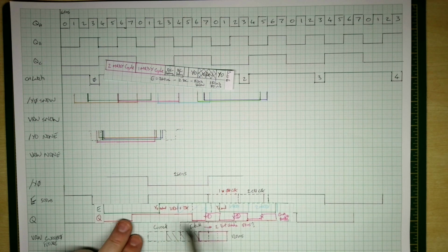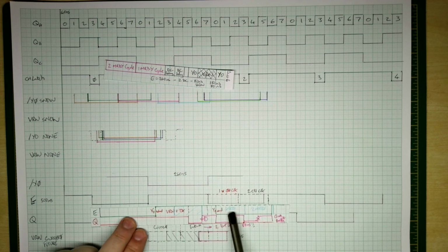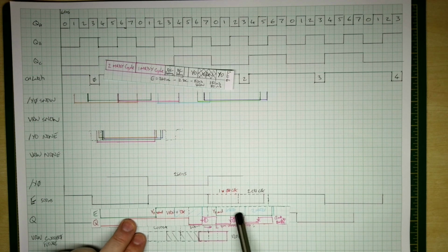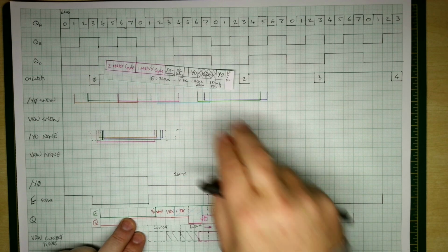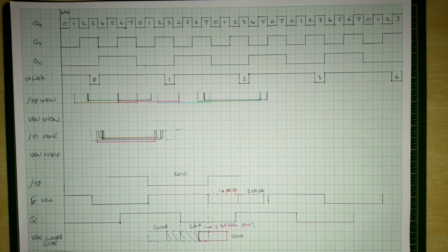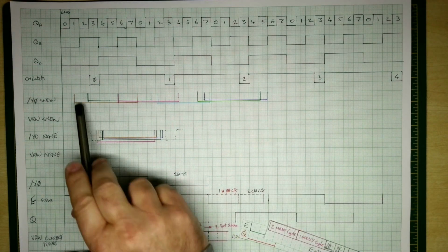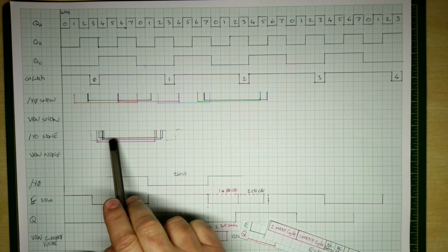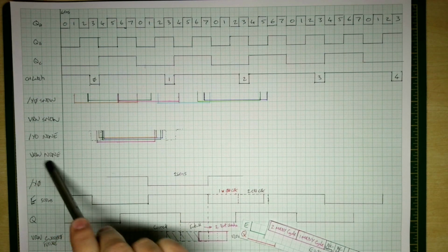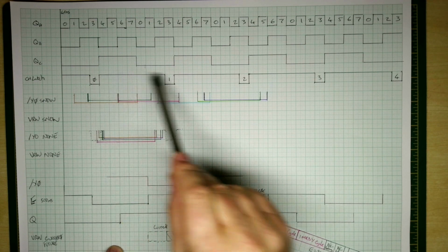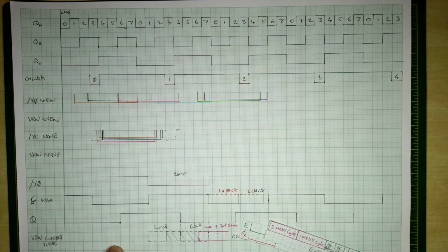This chart here as well just shows how, if we're adding various clock delays and things, then we can expand the period. So to cut a long story short, the analysis to work all this out, so all the logic analyzer signals are plotted there. It basically indicated that what we need to do is to make sure the Y0 and the video read write signals are within the two character latch values here. So there's a further analysis that I then did.